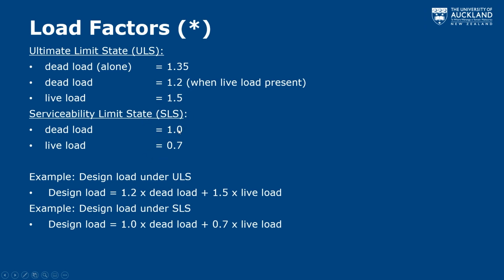However, at serviceability limit state, you can see that for dead load, our load factor is 1.0, so we're just taking that nominal load, that 95th percentile load. For live load, we're actually reducing down, and this is because on the day-to-day performance of, say, a floor, it's unlikely that you're going to be at full occupancy. If we want to make sure the floor is not deflecting too much or vibrating too much, we assume that most days, because the consequence is that the building is just a little bit annoying, we don't have to be nearly as conservative. And so we can take that reduction when we're doing the design.